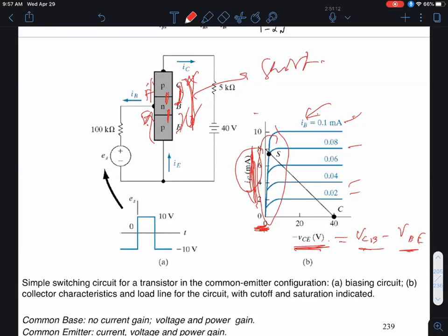Now, what is the impedance of the BJT under these conditions? Is it high or low? Well, impedance, or say resistance, in a normal resistor would be defined as V over I, but these are all voltage dependent resistors. So you have to define that as delta V over delta I, right? So is my impedance high or low under these conditions? Delta V is very small and I get a large delta I, right? So this is a very, very small number, or the conductance, which is the reciprocal of that, is a very large number. So it's almost like a short circuit.